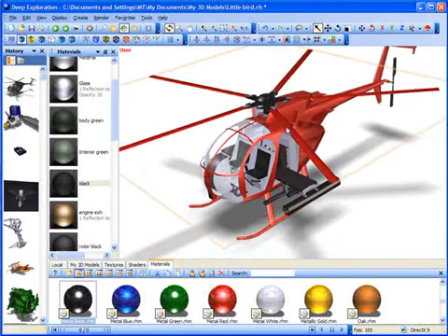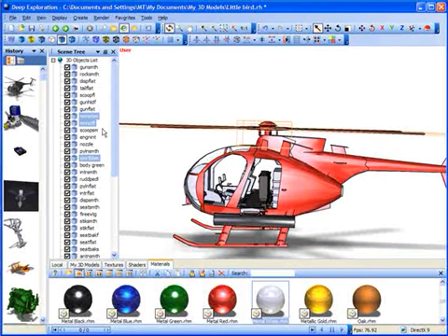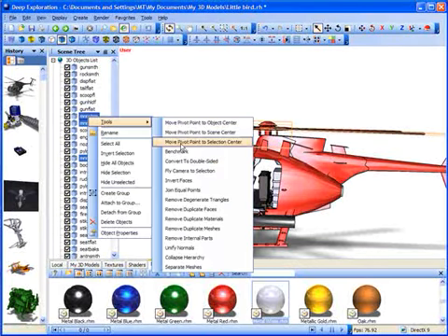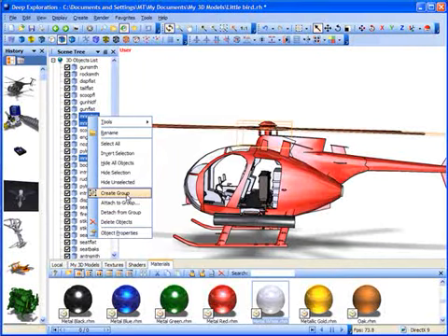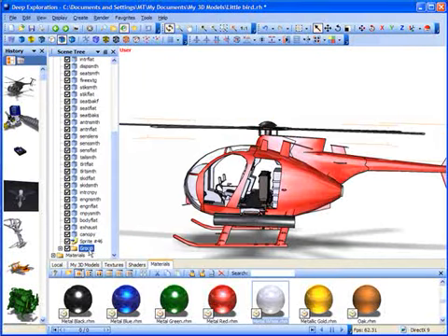So what we want to do here is to select all of the components, hit the control key. We'll choose in fact a rectangular selection, and we'll select all objects. We'll go to our scene tree, and we'll see that we've actually selected a variety of different components. We in fact want to create a group from these, and we'll call this group the rotor group.